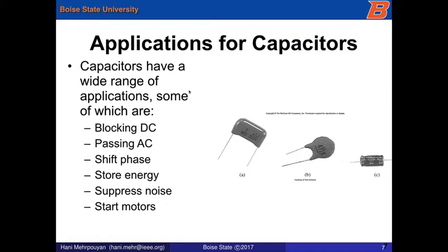So what are the applications of capacitors? Capacitors are very good at blocking DC signals, and we'll look at this very soon. They're very good at passing AC signals. So basically, capacitors make very good high-pass filters. They can be used to create that phase shift that we discussed, or the delay in the cycles.